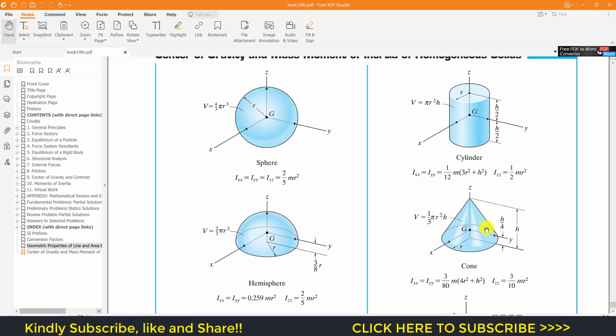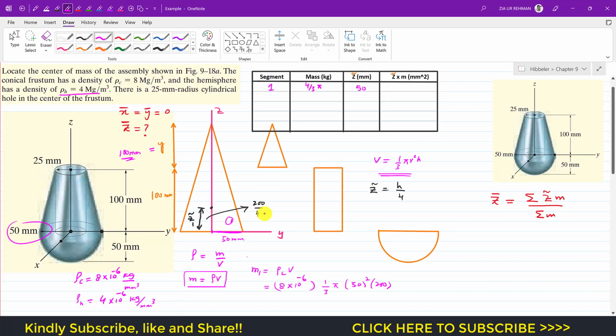From this table, we can see that if we are considering a cone, then its volume is 1 divided by 3 pi r square h, and its centroid is at a distance of h divided by 4 from its base. So we are using these formulas for calculating the z tilde of the cone. So that is h divided by 4. So h divided by 4 is 200 divided by 4, and that gives us 50. So z tilde 1 for segment 1 is 50.